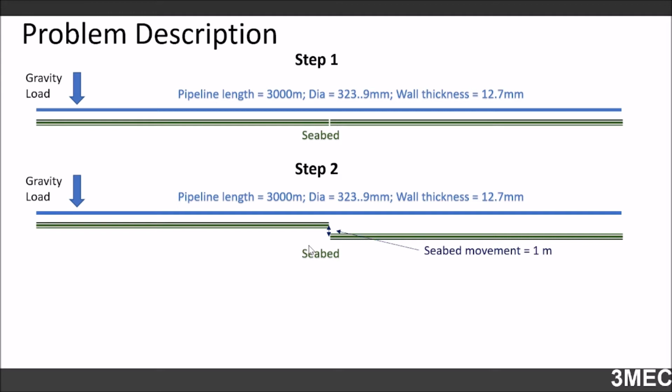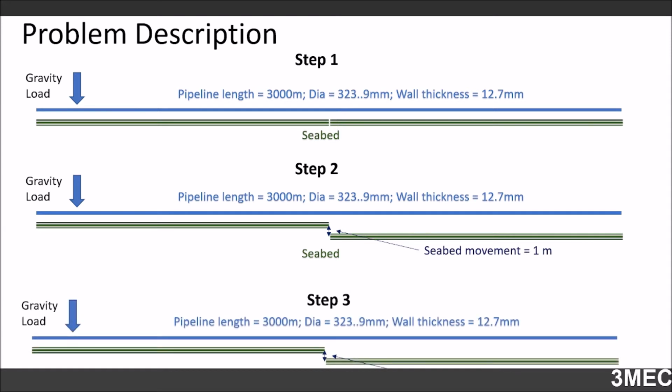Then we will apply the operating conditions, which will be temperatures in this case, and we will see what happens if the temperature goes up to 120 degrees. Generally 60 degrees is fine, but I have just used this random value to show the whole buckling curve for the effective axial force before and after the buckling.